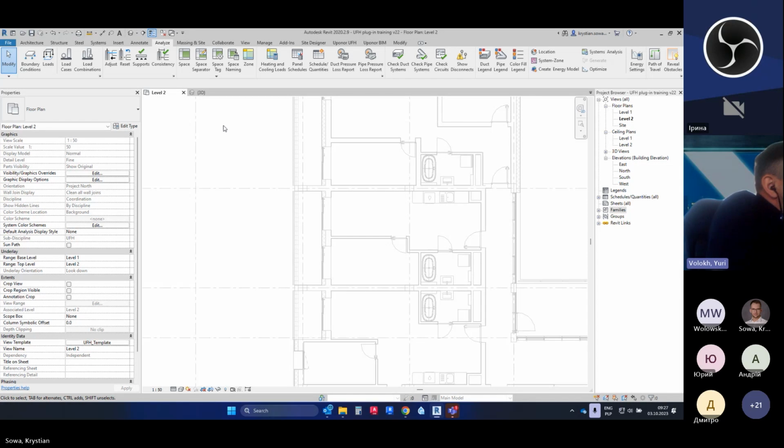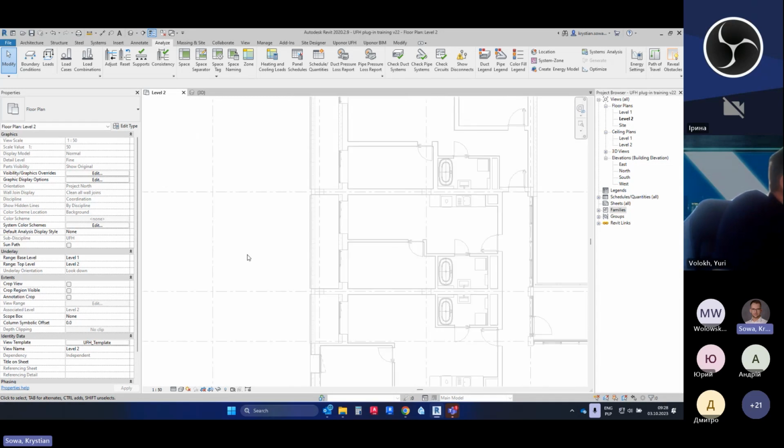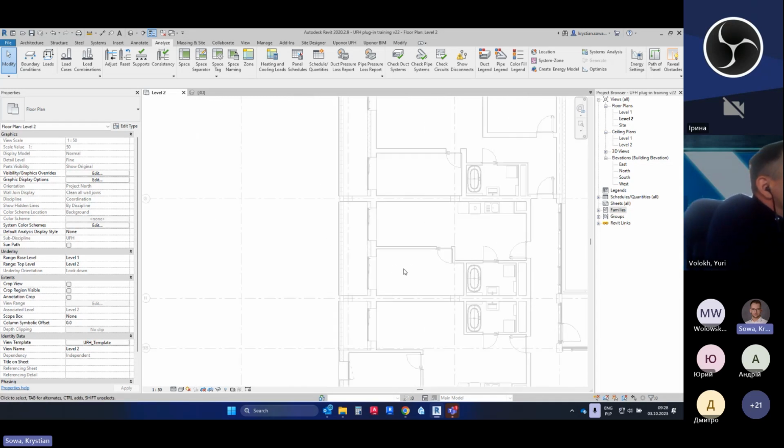Yeah, so as I understood you correctly, you already said that if there's no Revit file as an architecture, we would need to specify the borders of the spaces. So if you would have some IFC file or some DWG file or any other file that is not a Revit model, then you would need to create the borders first.